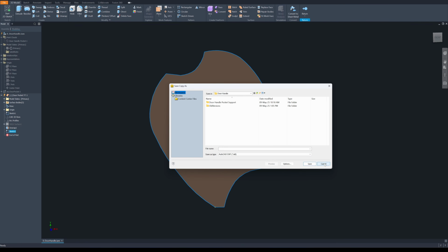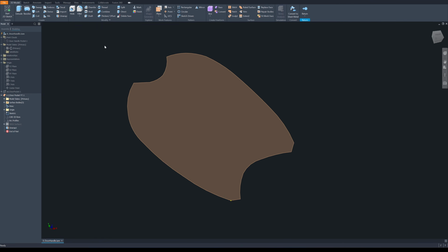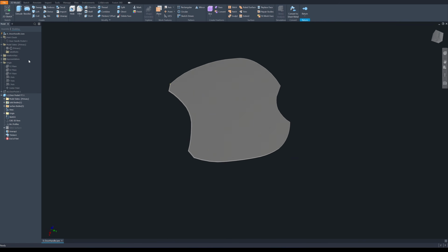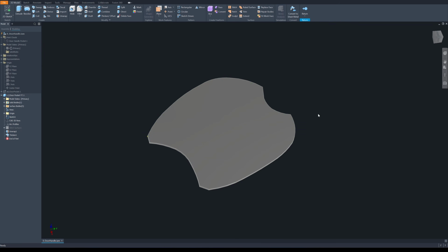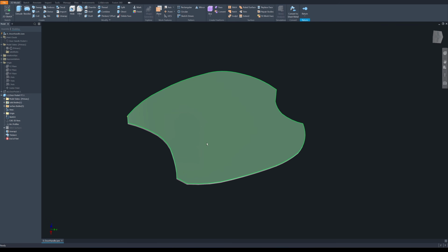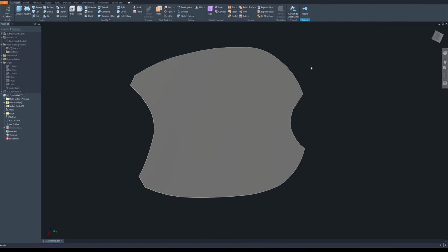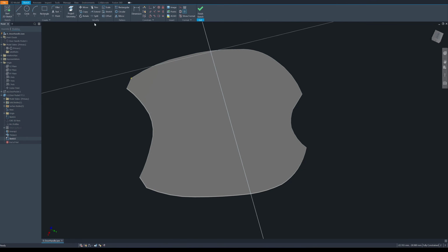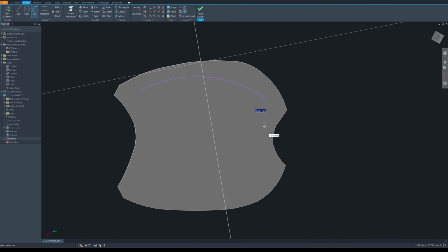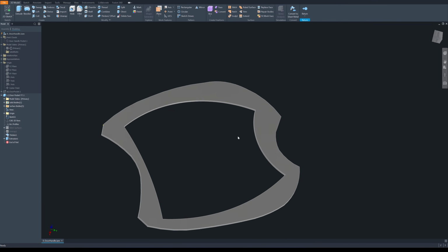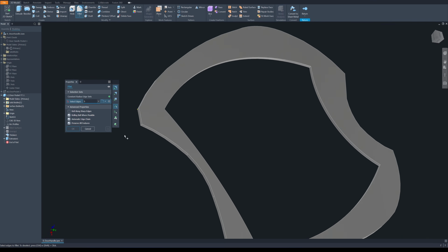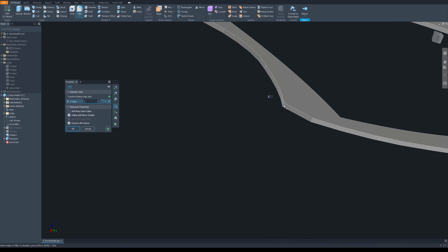I don't have a sticker cutting machine, so what I'm going to do is thicken this surface to 1 millimeter, and then print this one in the 3D printer, and use this template for hand cutting with a knife cutter. I want to save filament, so I will create a sketch here and cut the center, make an arc here. So I don't need anything in the center. I cut it out. Now we have a solid for printing, and I'm going to round some corners, 5 millimeters, so that we have round corners.